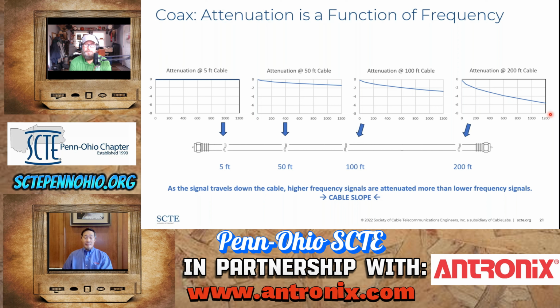As we mentioned, there's a lot of cable in some of these networks with longer cascades of amplifiers and segments of trunk cable and feeder cable. It's not unusual to end up with several miles of distribution and trunk cables inside of a node. And the more cable there is, the more that shape accumulates.